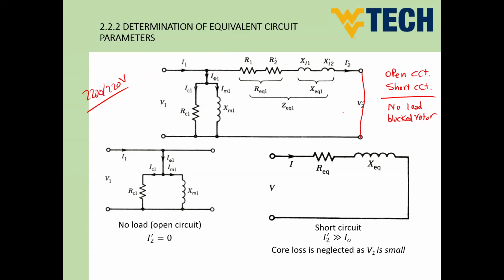Can you imagine how much current we would have if you make a short circuit on 2200 volt? It's a very huge current because the volt is very high. So in this test, guys, firstly, we will not make a short circuit at the rated volt. I'll discuss with you the procedure of the test, but just here, let's understand the concept in order to provide the circuit. So we will not apply the complete volt.